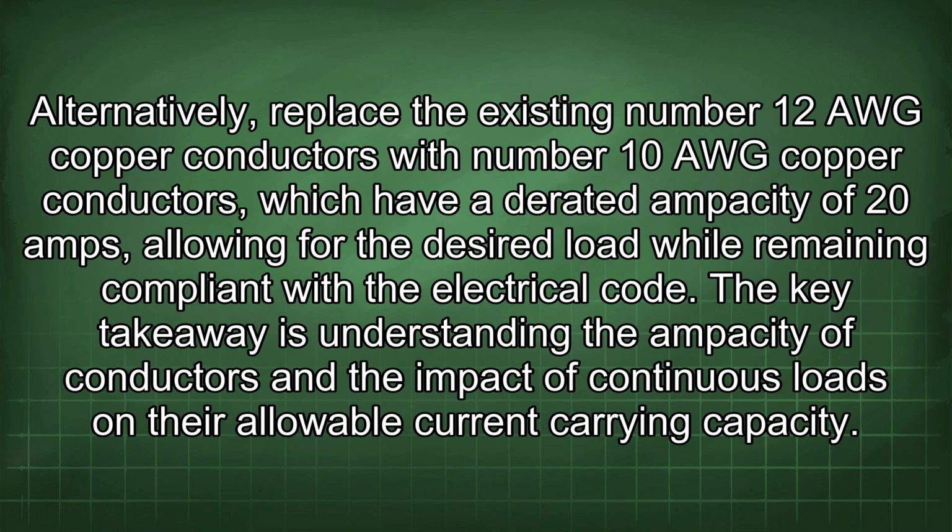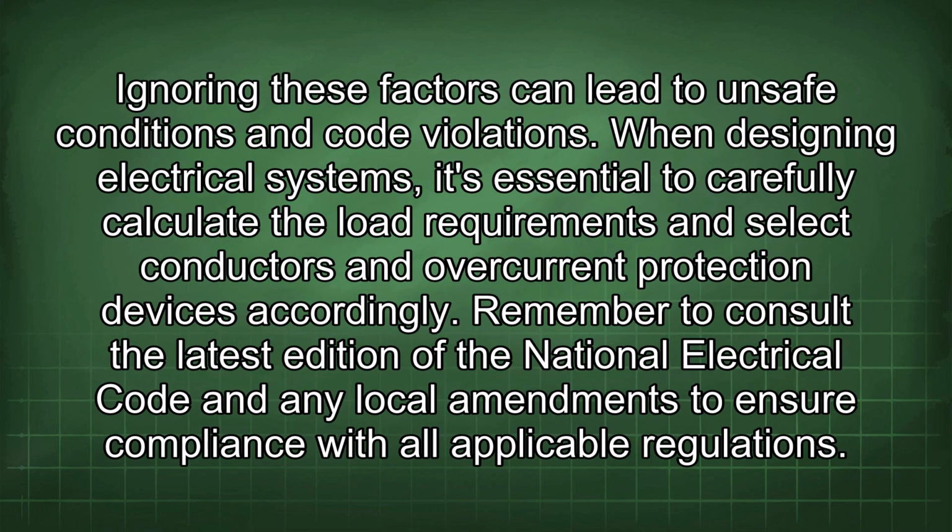The key takeaway is understanding the ampacity of conductors and the impact of continuous loads on their allowable current carrying capacity. Ignoring these factors can lead to unsafe conditions and code violations. When designing electrical systems, it's essential to carefully calculate the load requirements and select conductors and overcurrent protection devices accordingly. Remember to consult the latest edition of the National Electrical Code and any local amendments to ensure compliance with all